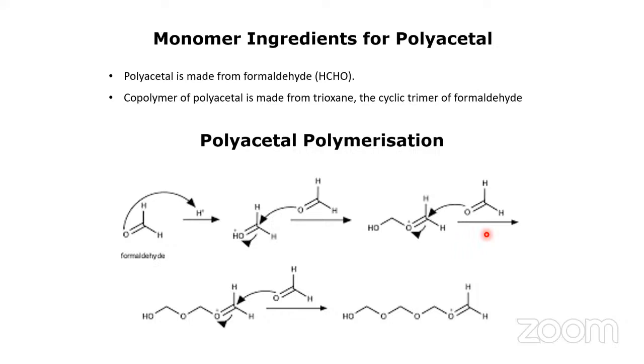Yes, sir. The example you can take is polyethylene. If you consider polyethylene, CH2, CH2, CH2, CH2, a continuous repeating carbon chain will be present. But in the case of polyacetal, you will observe oxygen present after each carbon, correct? Have you observed that near my cursor? That is oxygen. If you see the chain structure, it is nothing but CH2O, CH2O, CH2O in that way.